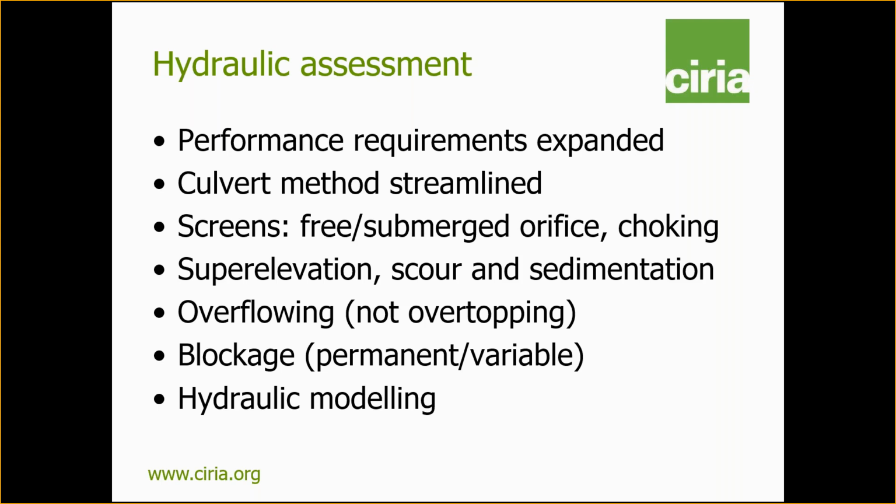We've renamed overtopping as overflowing for consistency with the ICE floods and reservoir safety. And the manual also defines permanent blockage and variable blockage in line with the structural Eurocodes. The hydraulic modelling guidance no longer cites specific software packages due to the fast pace of the market, but guidance on modelling complex scenarios has been expanded to include blockage and screens.